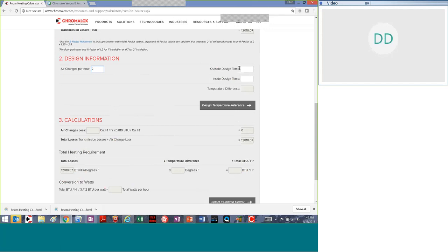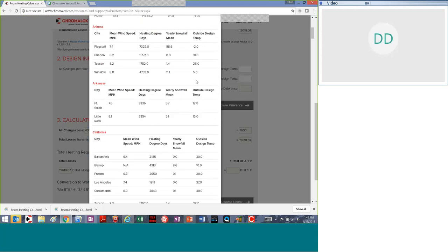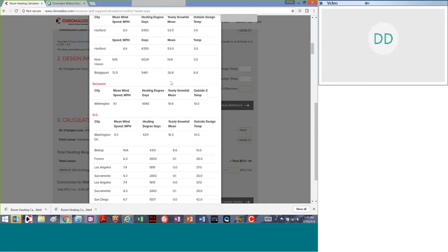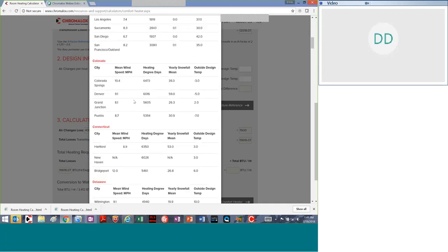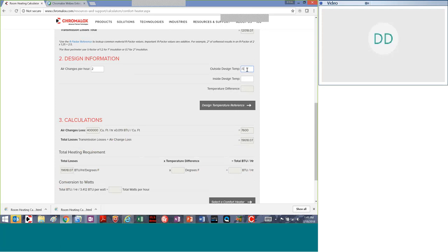I'm almost there, and we'll get to the discussion in a minute. Outside design temperature. Back to those charts, this is the minimum, but worst case scenario. Now, they're loaded on here from ASHRAE charts. You can look them up online. In the case I'm in Colorado, Denver, let's use -5.